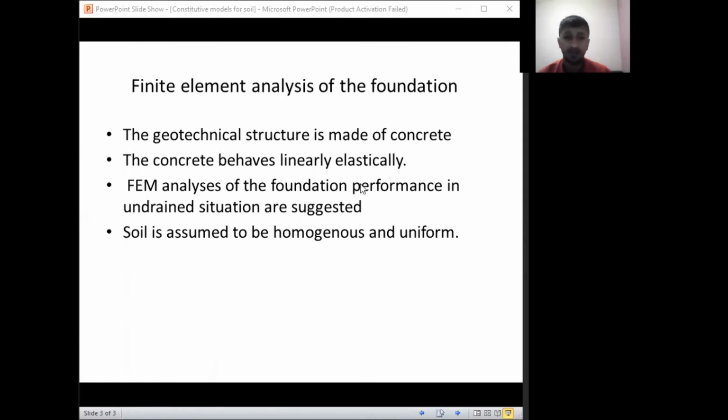However, we solve the linear problem where the material behaves linear elastic with small displacement and small strain. If it is a non-linear material, then there will be large displacement and large strain. And during evaluating the performance of the foundation, the simulation may be stopped at the settlement of 0.1 B. If it is found that the ultimate failure load does not exist, the validation of FEM results should be performed. So we will choose linear elastic material and shallow footing for the analysis.